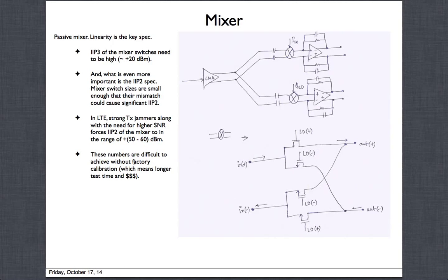factory calibration. So what we do in the factory is, every phone that is made goes through a calibration. We calibrate many things, and one of them is this. We'll actually put two close-by tones into that particular phone. We load up the phone on the setup, with measurement equipment and all. We'll put in two inputs, and we'll measure what the output is.